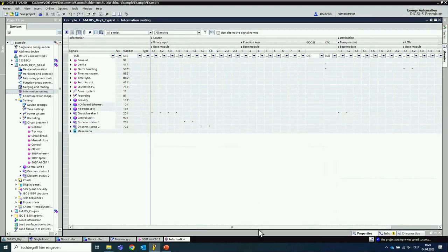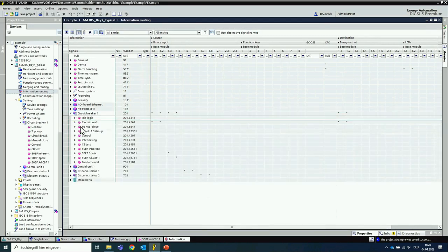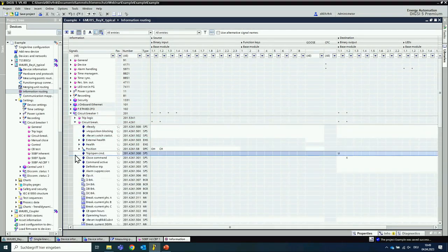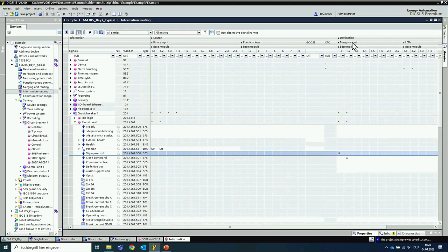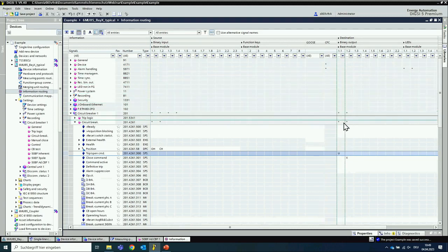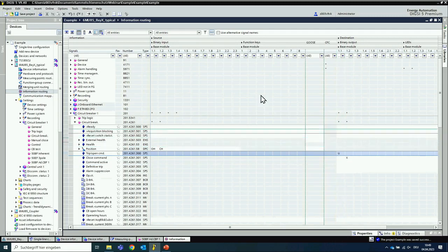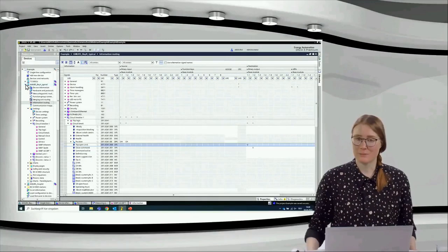And then, of course, we do not only need binary inputs, but also binary outputs to transmit the trip signal to the circuit breaker. So I open again the circuit breaker here and go to circuit breaker again. And here you can see this trip open command. This is the one you should connect to your circuit breaker. And you can see here also under binary output that this signal is per default routed to the output 1.1. And this is fine for me. I just leave it like this. And this is all I want to do for our 6MU85 bay typical for the moment.